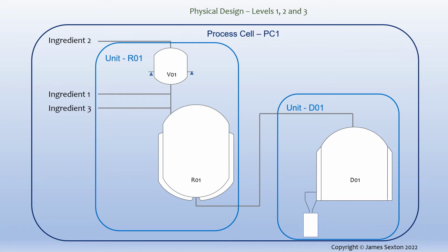The crucial points here are that an equipment module is defined by the processing it does and where it does it. Since vessel V1 is to be used to weigh ingredients, it qualifies as an equipment module on the grounds that it executes a minor processing task, weighing of material, and we can see that the process equipment where the weighing happens is in the weigh tank V1.